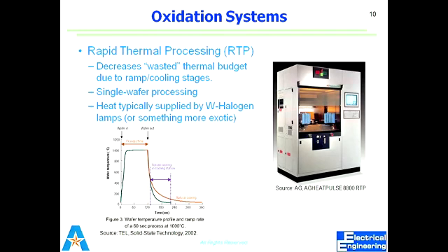But you know that the quality would be better, but what would be the problem with dry oxidation? What is the limitation of dry oxidation? That is actually the thickness, that is the oxidation rate. The oxidation rate is very low, so you cannot grow a thick layer of oxide. If you want to grow 1 micron, you cannot do it with dry oxidation. You will have to go to wet oxidation. Okay, but yes, he is right that whether it's a horizontal or a vertical furnace, you can use both dry or wet oxidation.